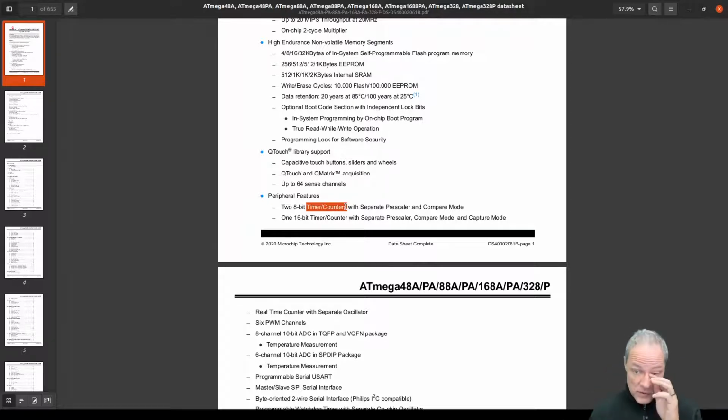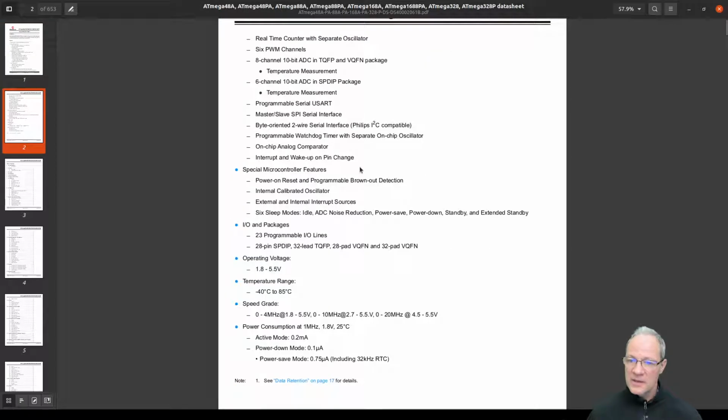It may have several modes. It may have a one-shot alarm, where it's going to ring only once, or it may have a repetitive mode, where it's going to ring every once in a while, depending on how often you want it to create an interrupt. That way you can use it for your programs. And apparently there are 2 of these timers. One is 8-bit, meaning that it can only count up to 256. So that's not too far away. And then you have a 16-bit timer, which is a bit finer resolution, and we can use it as such.